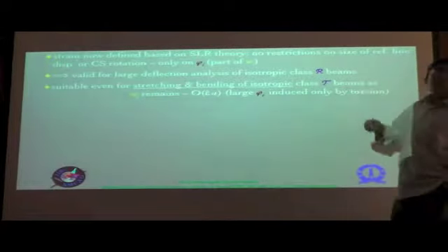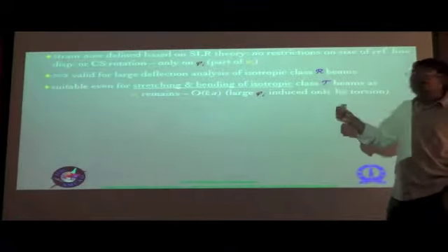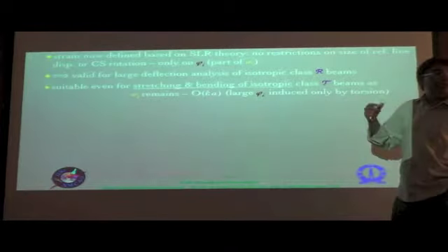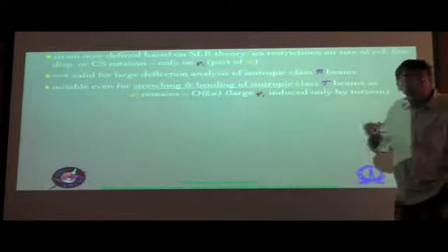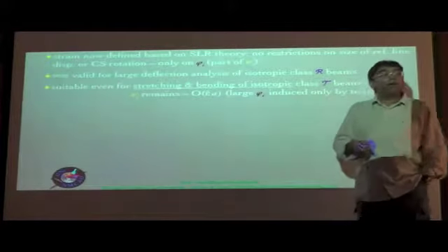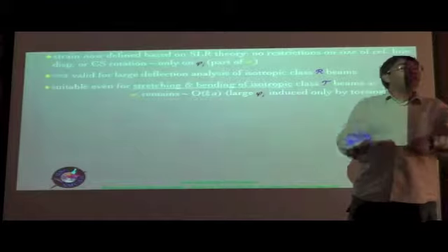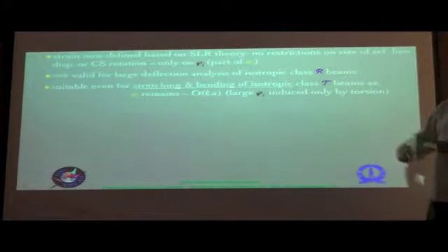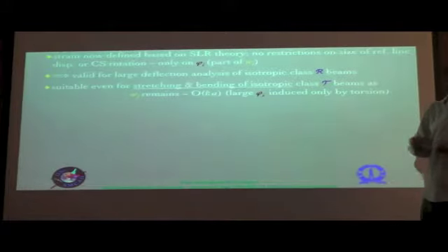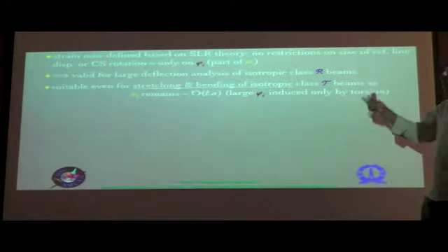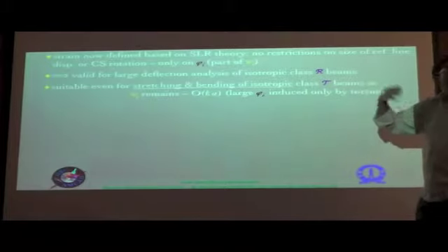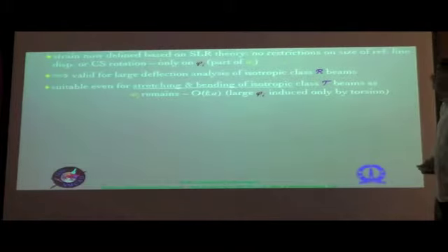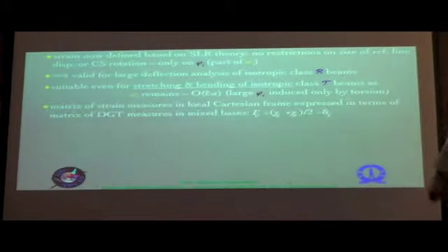That's what typically happens with class T beams, but only in situations where there is torsion, because both the class T beams as well as class S beams for that matter are very soft in torsion, and that's where the rotations are much larger, and the corresponding local rotations are large as well, or rather larger compared to the usual thing, what we call as moderate local rotation theory instead of small local rotation theory.